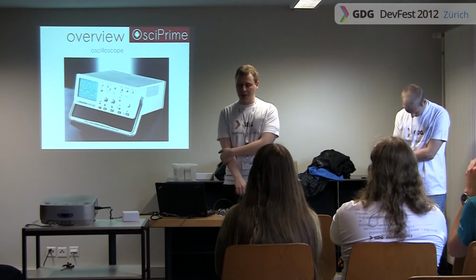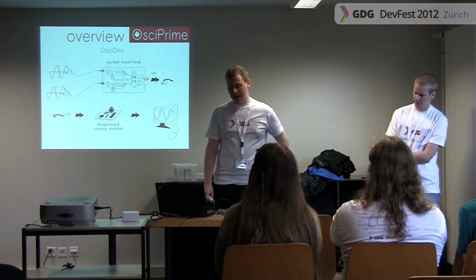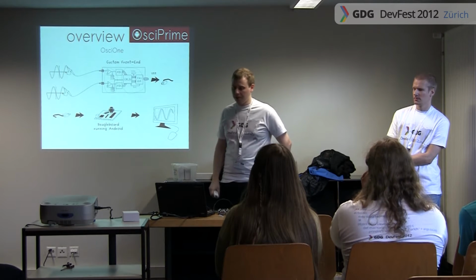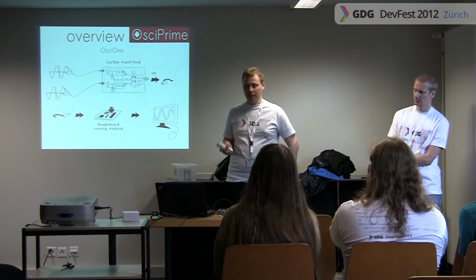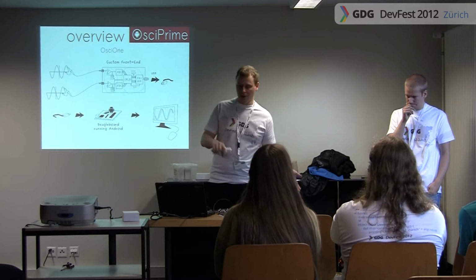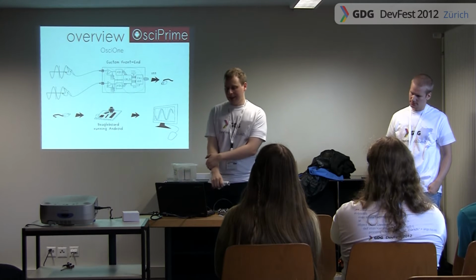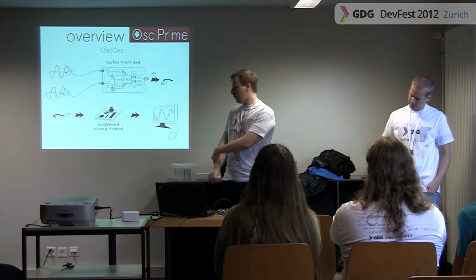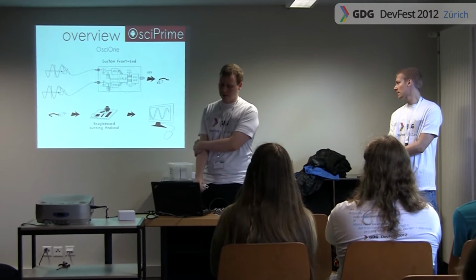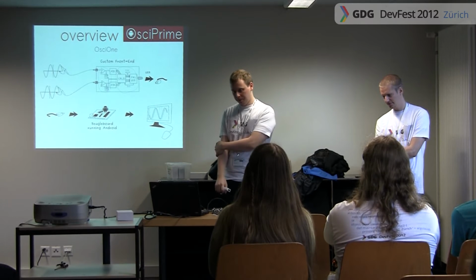Okay, so our goal was to create something like this, however, in a bit different form factor. As you can see in the picture, we would have, for the OsciOne project, which was the bachelor thesis, a hardware front end, which you can see on the top, where we have AD converters, some low-level logic, a CPLD, a USB controller, and then we would take this data and ship it over to an Android application, which we would run at that time on the Beagle board. And then the user interface was a screen with a mouse and a keyboard. So pretty classic. You could take a computer for that. However, it is much more low power and much more fit for industrial purpose if you have an embedded system.